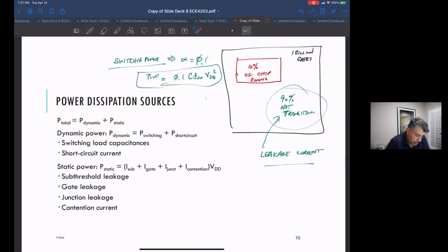operating mode. Now the dynamic power we just talked about comes from the switching power. So that's the alpha C V squared F. And this one we said is like 10% of switching power. You still have to keep track of it, I guess, but we said it's negligible for the most part. So that's all these components.